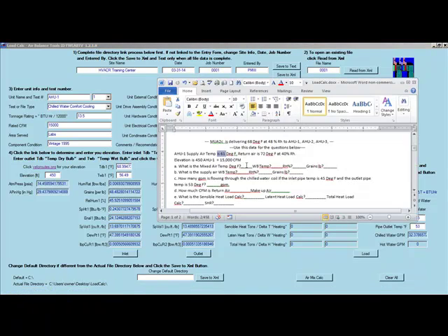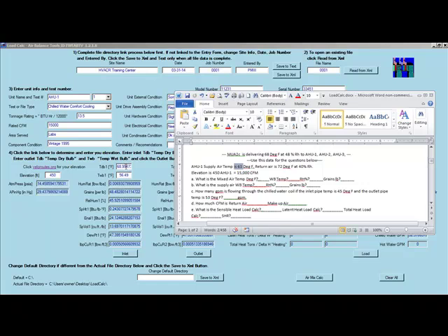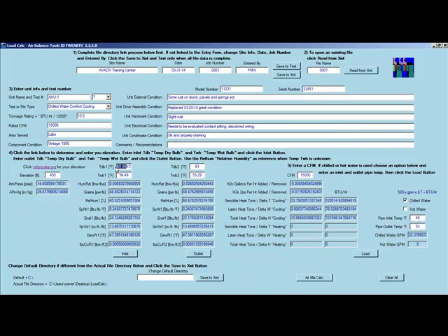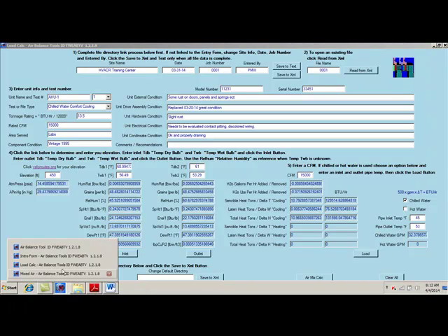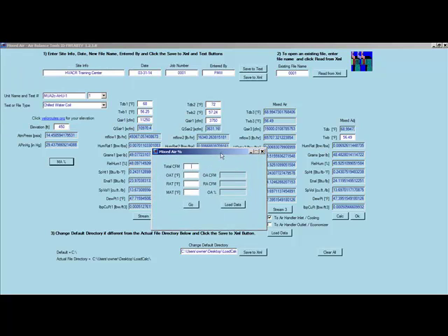So in this case we would say, what's the mixed air temperature? Well, our mixed air temperature, we still have it, it's right here, and we can say 69. Oh, I missed a step. Let's go back. This mixed air temperature, how do I know what my cubic feet of air is between these two values? Well, what I want to do is take this mixed air calculator and say, we know the outlet of this machine is 15,000 CFM.